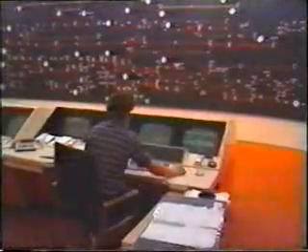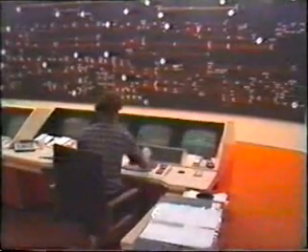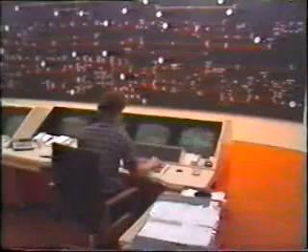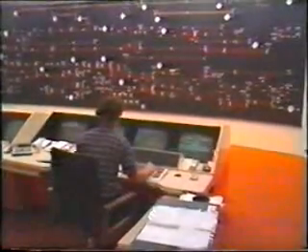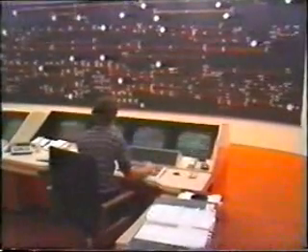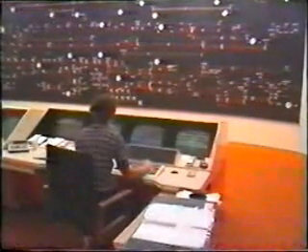If the power angle exceeds 90 degrees, then the power transfer will be reduced, and the system will probably fall out of synchronism. For stable operation, the system operator loads the system in such a manner that the load angle across each transmission line is much lower than 90 degrees.